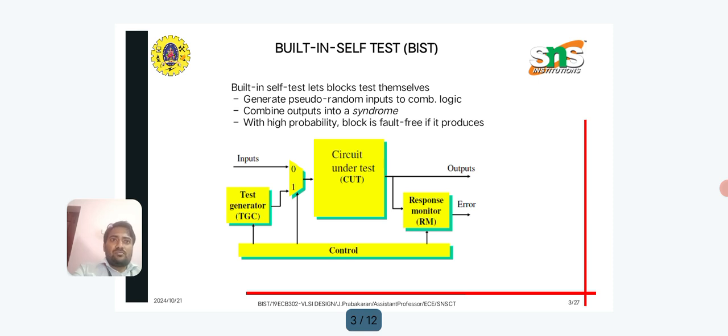Test access mechanism provides the interface between the internal built-in self-test circuitry and external devices. In systems using Joint Test Action Group or boundary scan, the test access mechanism allows external control and observation of the BIST process, facilitating debugging or system fabrication. Also, the test access mechanism can be used to initiate BIST operation or report the result of the test.